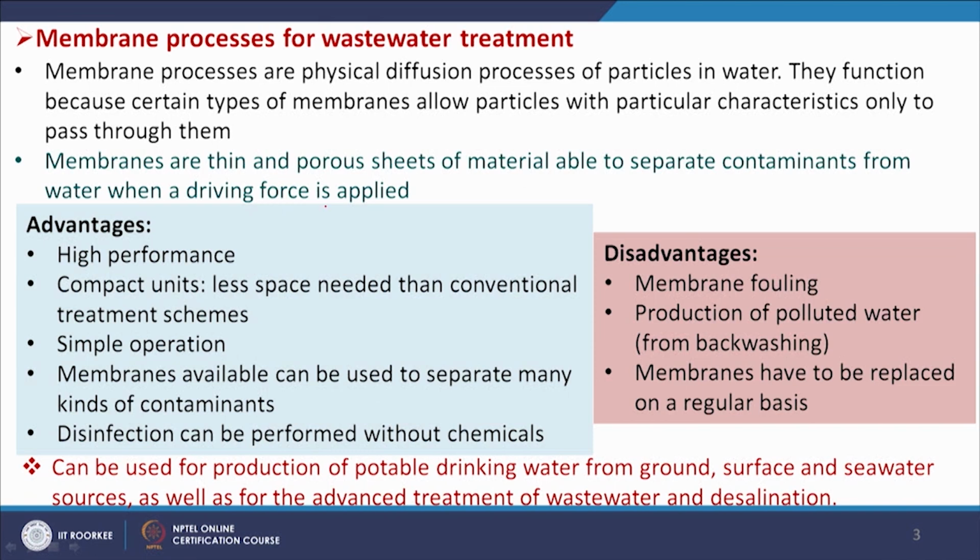This method has many advantages: performance is very high, it is a very compact unit, it requires very little floor area, much less space than conventional treatment schemes, and simple operation. Membranes available can be used to separate many kinds of contaminants, and disinfection can be performed without chemicals.